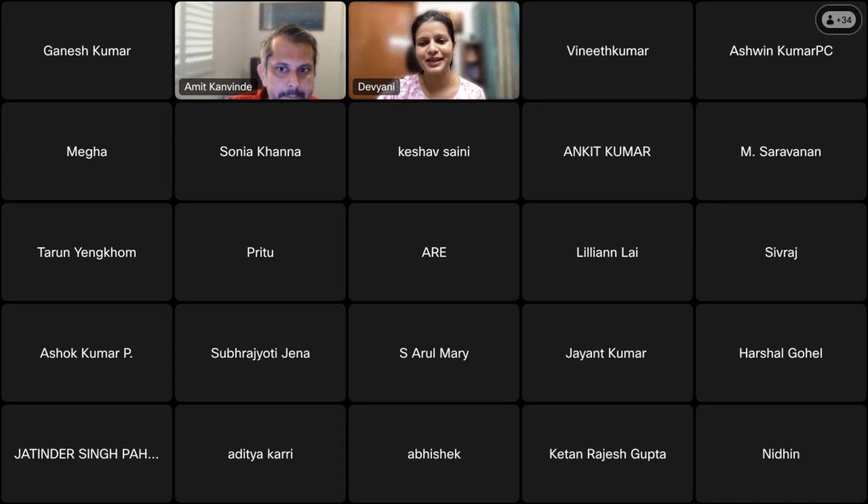So yes, the last question will be from Mr. Tamil Selvan. While selecting weld electrode to be used for welding near connections, how do we have to select it, whether we have to go for overmatching or balanced kind of weld electrode? If we are selecting very high strength electrode, it may have less ductility. So how do we address this issue?